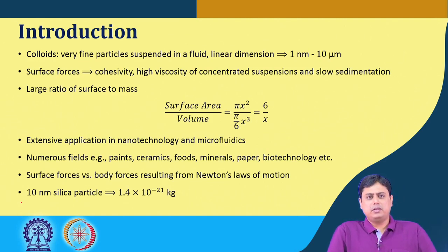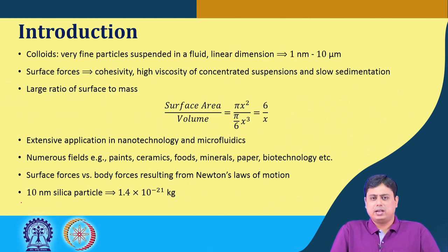They can exhibit the behavior of high viscosity of concentrated suspension, and they also result in very slow sedimentation. That is why we spoke about sedimentation in some external field like the centrifugal field, because by gravity separation this kind of fine particles cannot be separated. These remain suspended for a longer time.